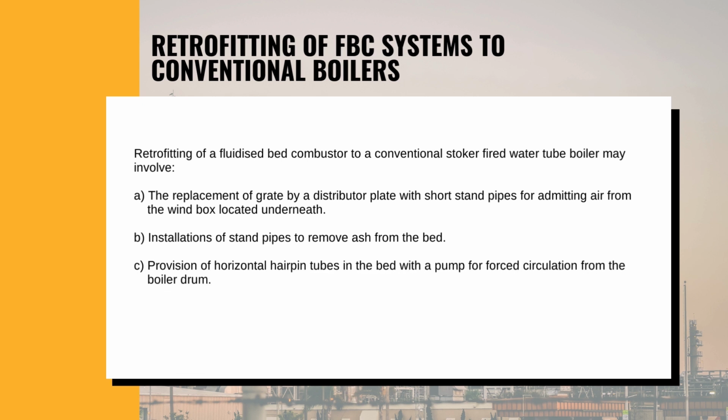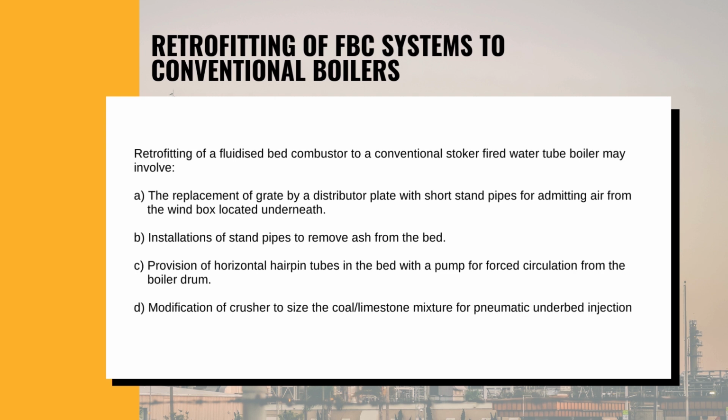Retrofitting of a fluidized bed combustor to a conventional stoker fired water tube boiler may involve the replacement of grate by a distributor plate with short stand pipes for admitting air from the wind box located underneath, installation of stand pipes to remove ash from the bed, provision of horizontal hairpin tubes in the bed with a pump for forced circulation from the boiler drum, and modification of crusher to size the coal or limestone mixture for pneumatic underbed injection of the mixture.